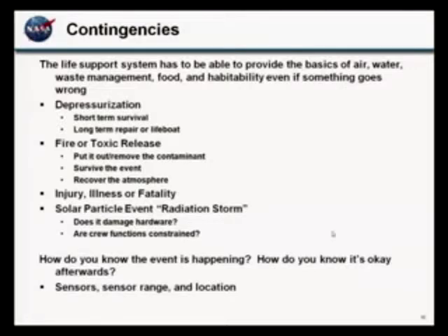So depress, and feed the leak, is also one of those things that can drive you to maybe not different functions, but different technology choices and different system sizing, right? The function is always provide oxygen, but provide 50 pounds of oxygen an hour for however long is considerably different than provide 4 kilograms of oxygen a day. Your electrolysis system is not going to be sized to pump out enough oxygen to feed a leak. So you better be able to provide it some other way.